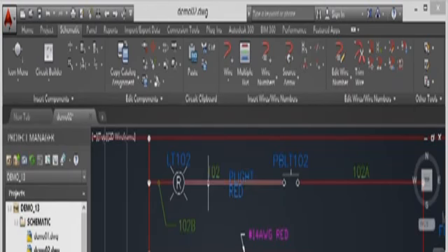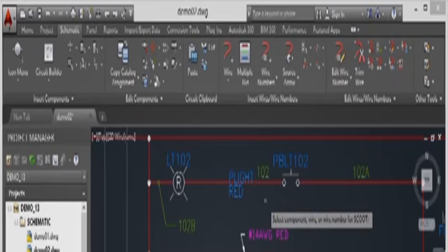Let's have a look at this one at the top. It's a little bit more crowded up here. What I'm going to do is utilize Scoot first. I'm going to go up to the Scoot here on the Edit Components panel and select that wire number there. Little box appears. I can scoot that along to here just for now and then press enter to finish.